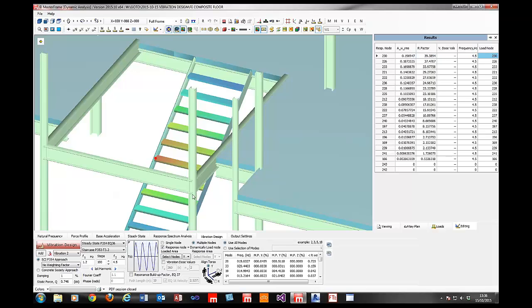So now looking at this here, if we did say, right, well, we did really want the response factor to be below 30, it's worthwhile considering before we start increasing section sizes or changing mass, whether or not we can make use of something called vibration dose values. Now, this isn't just applicable to stairs, but for any floor or stair.